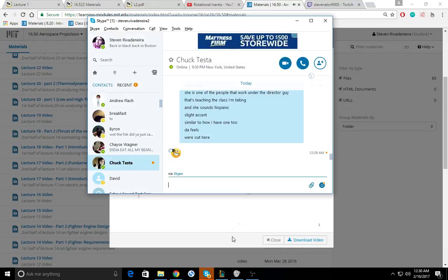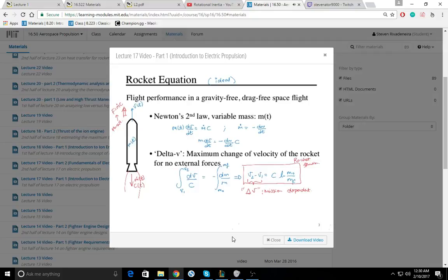The rocket equation, which is this equation here, relates the type of engine that we need, which is given by the exhaust speed. This is engine dependent. To the mission that we want to accomplish, and here we can see that the higher the exhaust velocity, the greater the mass fraction that we can bring into orbit for a required delta V. So this is the rocket equation that you derived the other day in class.